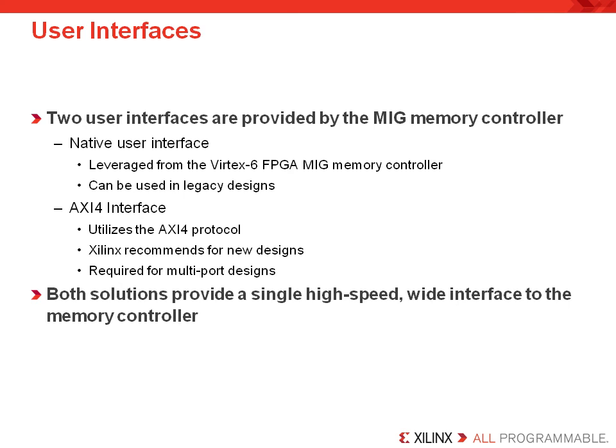Now there are 2 user interfaces that are provided with the memory interface generator. There's a native user interface, which is leveraged from the Virtex 6 FPGA MIG memory controllers, and it can be used in legacy designs as well. There's also the AXI 4 interface, which we've been moving to, which utilizes the AXI 4 protocol, and we recommend it for new designs, and it is required if you're building multi-port designs.